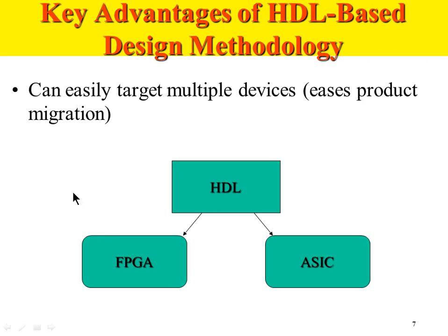No technology dependent components of this FPGA should be included in my Verilog code. If I do that, I can call my Verilog code technology independent. If I have technology independent Verilog code, I can target it to other devices later on. If I have certain technology dependent components, then I have to make changes where similar components from the other technology are used.